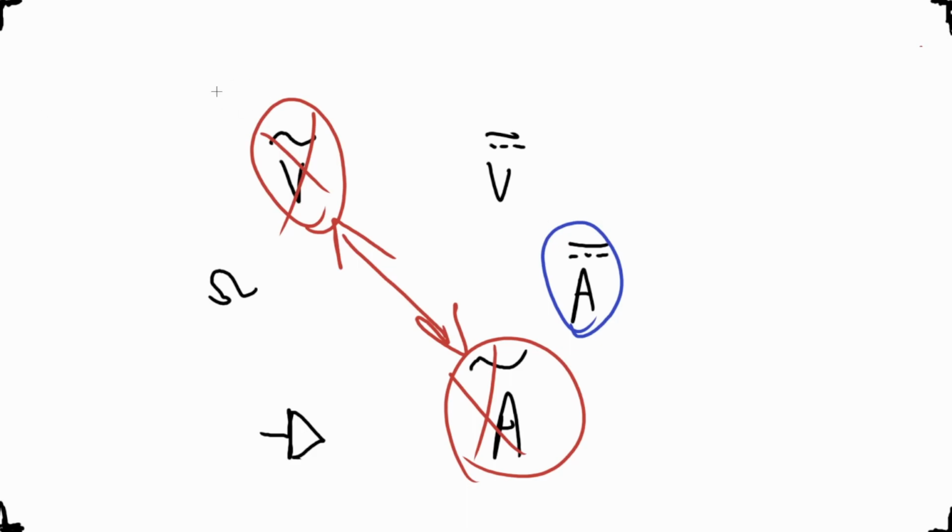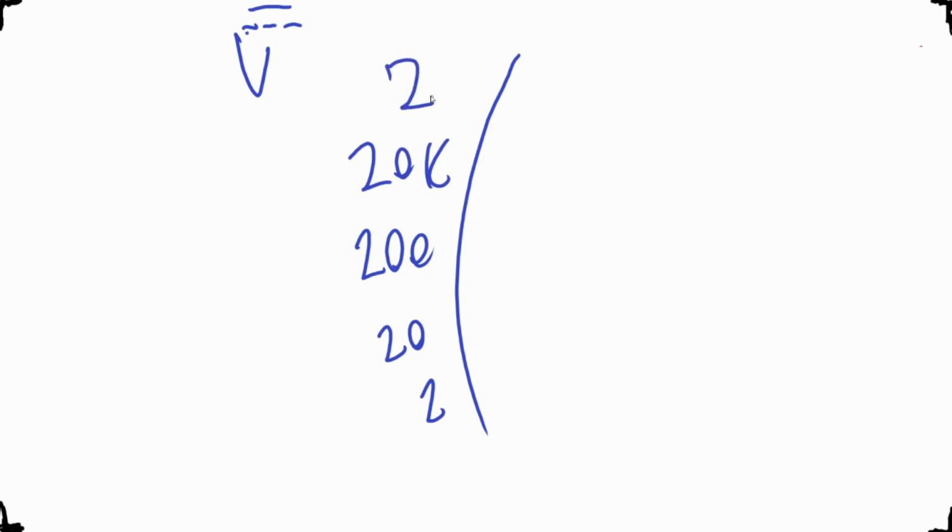Now, if you go ahead and actually look at a multimeter on the day, you'll see that the value looks a bit weird. The whole thing will be a dial, but zooming in on that dial further, we'll take the voltage as an example. You'll see something along the lines of 220, 220K, 2M. This is all over the place. These numbers are kind of irrelevant. But what this actually means is it's indicating the scale of what the multimeter is reading.